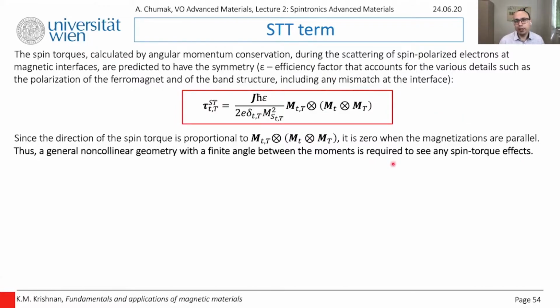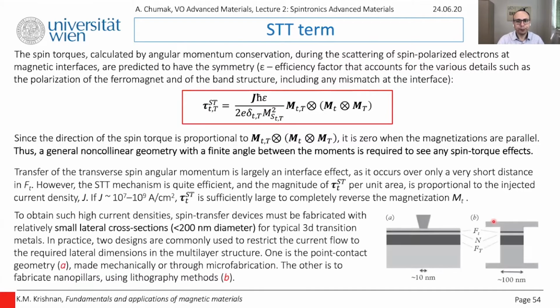But we should not forget that in all real situations, we always have some fluctuations of magnetization, and therefore if you apply current even in this anti-parallel state, one little fluctuation is sufficient just to start the switching process, and then it will be enhanced, and torque will be maximized, and then you will get switch of the magnetization like you need.